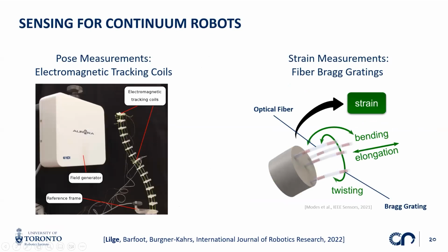So the way that works, these fiber Bragg gratings have discrete gratings along their length at which the light is reflected. So at every one of these discrete points, you get a measurement of strain or position, if the software already does some reconstruction. In this case, I think we would have gotten up to 20 or 30 measurements.